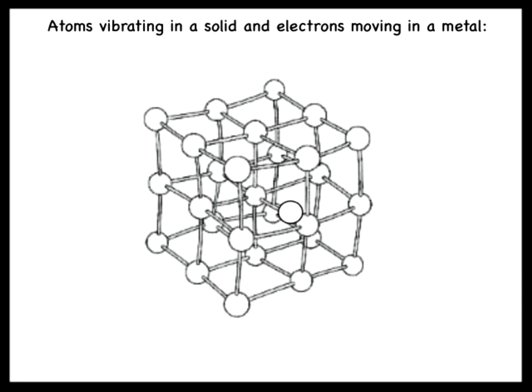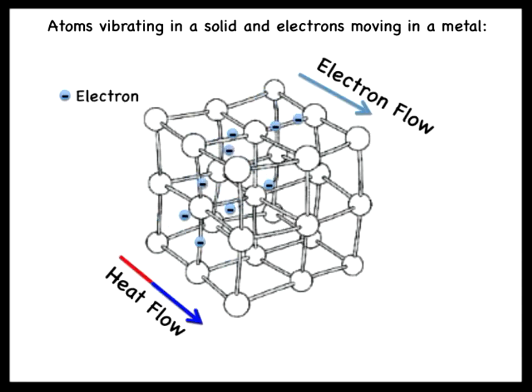Metals, like copper, are good conductors of heat. They take advantage of electrons that are free to move throughout their volume. These free electrons can transport energy and are responsible for the metal's good thermal conduction. As we will see in Chapter 20, these free electrons are also responsible for a metal's excellent electrical conductivity.